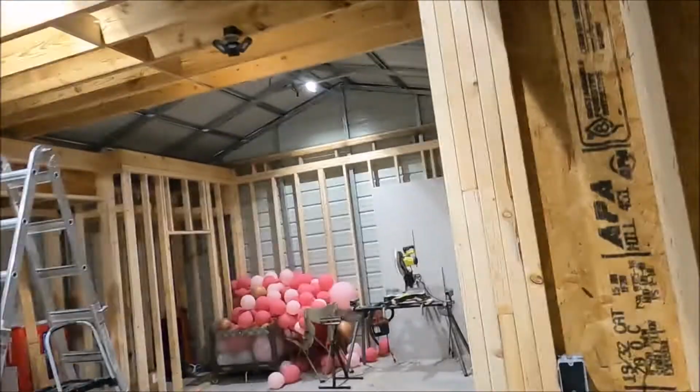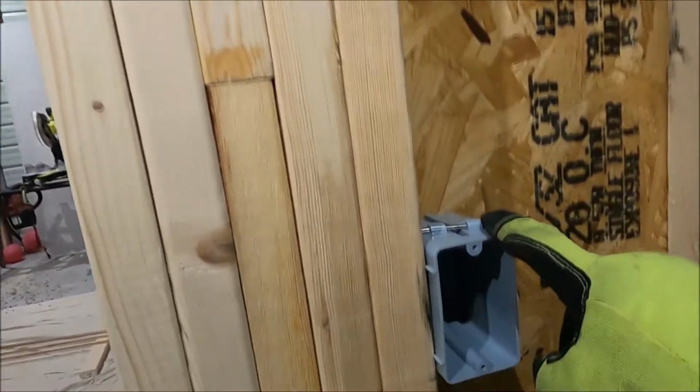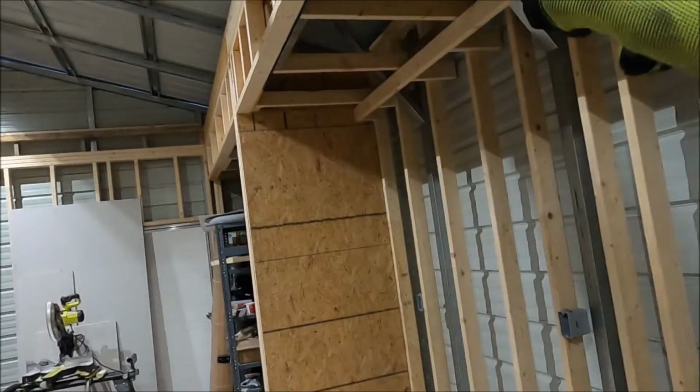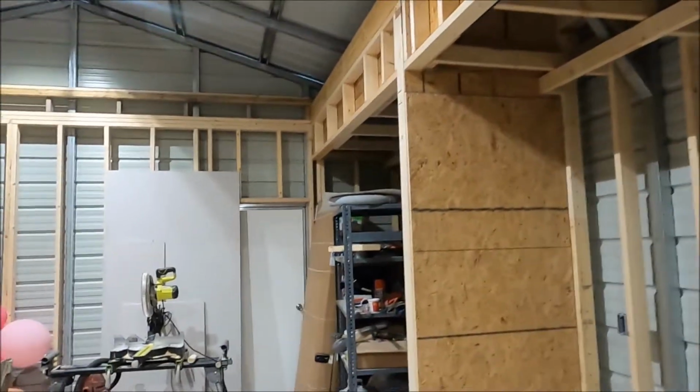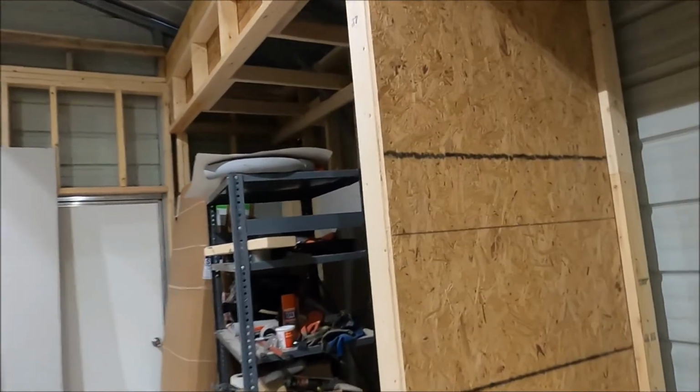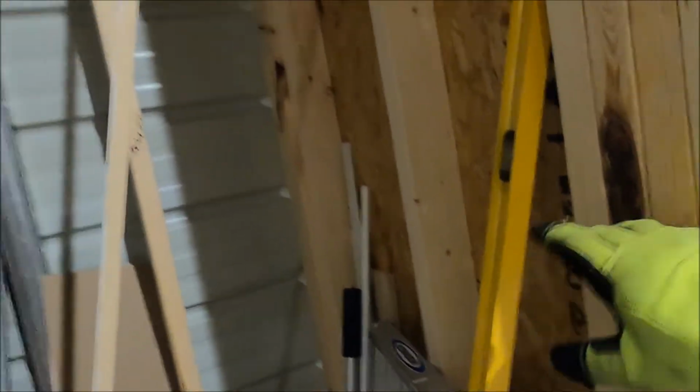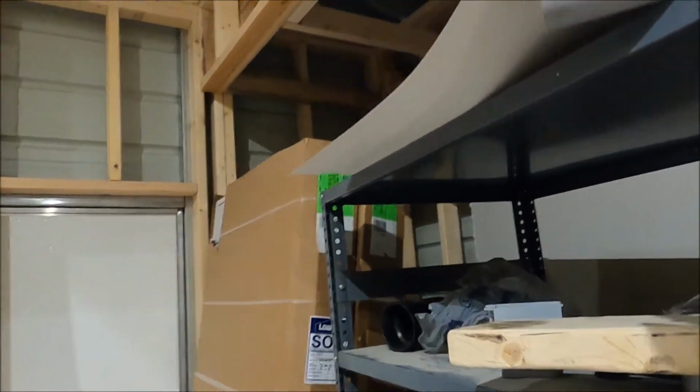Now that I have the hot running out of the panel box, the hot wire is going to come into this box and it powers that light. But what I need to do now is run a wire that's going to always be hot from this box over to this box, which is going to make this area light up. Then the hot wire is going to come over to another box that's going to be right here that I can't get to right now, which will power this light up here.